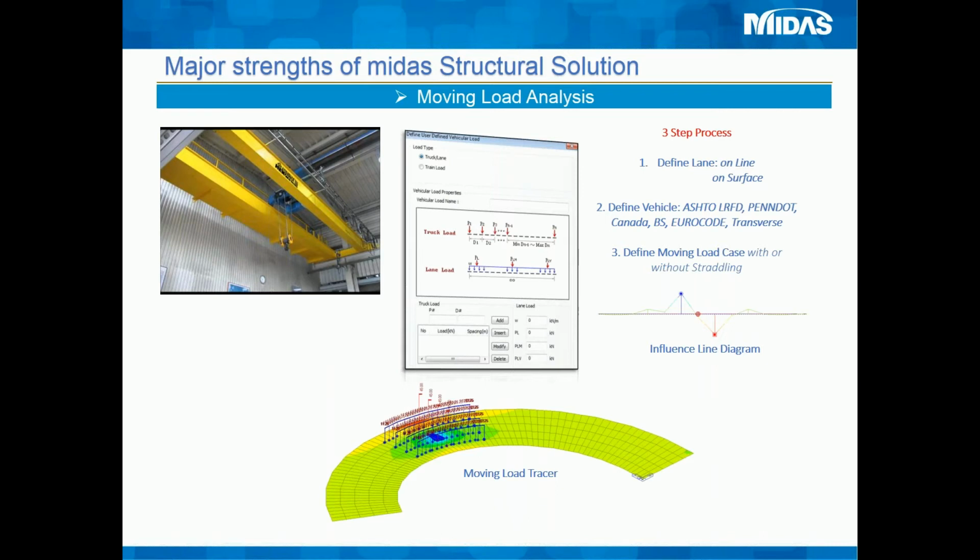Regarding moving load analysis, a huge amount of time is saved in this tool. The program, as a result, can provide us the location of the wheels due to which an element experiences maximum moments and forces. All the iterations of applying the point loads are eliminated here, thus saving a huge amount of time.